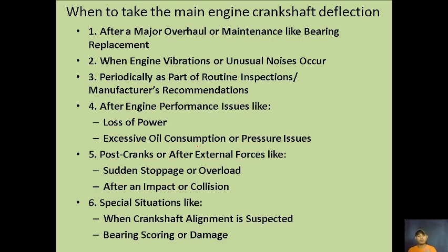Number 5, after external forces like sudden stoppage or overload of the engine, or after an impact of the ship, collision or grounding, you should do a crankshaft deflection. Or in special situations, like when you suspect that there is a problem in the crankshaft alignment, so to double check, use a crankshaft deflection. And when you see bearing scoring or damage, you should always do a crankshaft deflection.